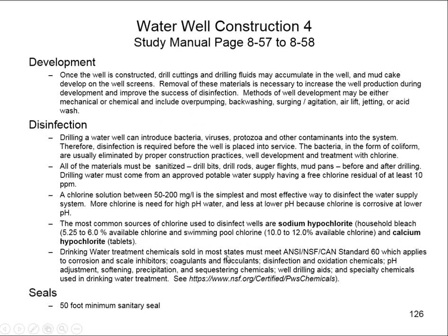If your swimming pool chlorine meets the standard, which would be on the outside of the packaging, then it would be safe to use in a drinking water well. So I would read those labels very carefully, but chances are this swimming pool chlorine is going to have too much chlorine percentage for you to be able to use it if you didn't have household bleach.